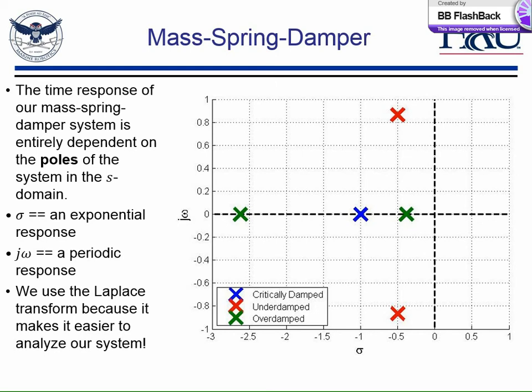we want our systems to behave kind of like second-order systems. And oftentimes we'll have more poles in our transfer function, or closed-loop transfer function, than the two that we typically have with a second-order system. So one thing to note is that as you make your poles more negative, the faster that transient response will go, and that term will die out. Right? So if we look at these poles, we see for the overdamped case that we have a pole that's all the way out by -3. That pole is going to die out much quicker than the pole that's going to be at -0.5. So our system, we can pretty much almost approximate it as a first-order system with a pole at 0.5. And one thing about the shape of these, right?